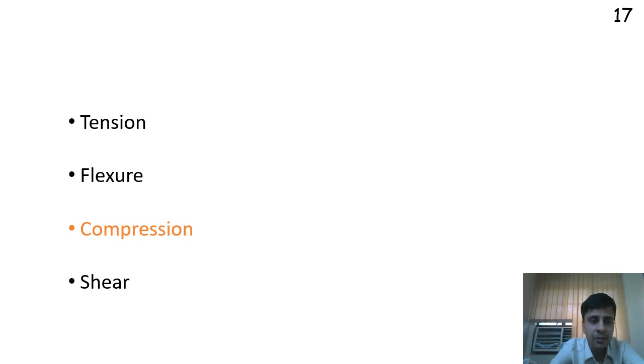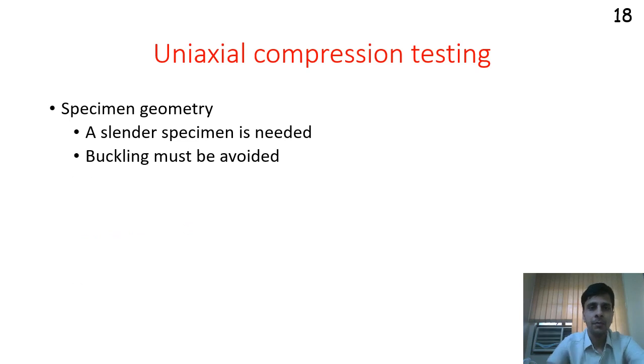So tension is done, flexural is done. Now let us look at compression. Compression testing is basically you take a sample and you want to find out what is the strength if you apply compression, as opposed to this is tension and your compression would be you try to press it. Now compression testing is usually tougher than tensile testing.